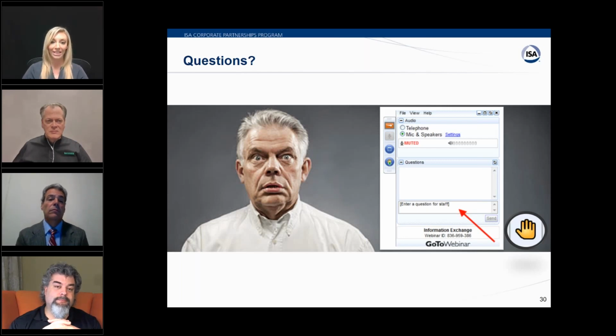Our first question is, why would the oil and gas industry rely on switches rather than transmitters? Well, this is Paul. I'll take a shot at that. Switches have been used for virtually 100 years, and people were using relay logic for safety systems up until the 1970s. And relays obviously don't understand what to do with a 4 to 20 milliamp signal. So switches are actually still the most common input into devices even today.